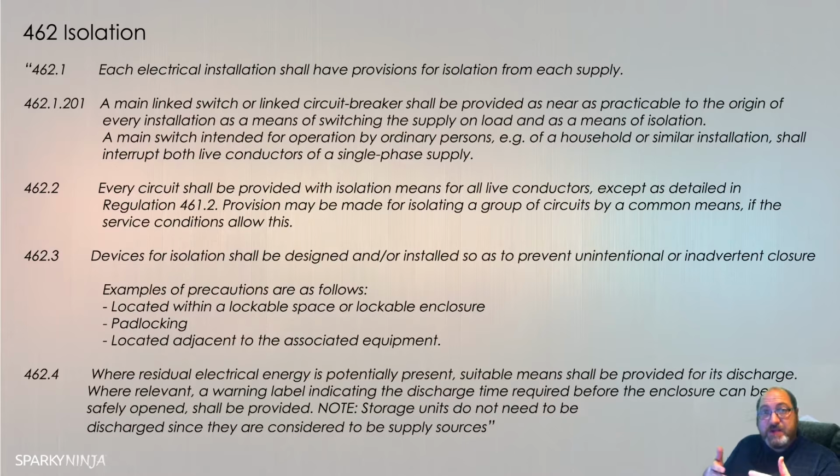The capacitor stores charge. If you work with power factor correction equipment or with any other electrical equipment that has a significant quantity of stored capacitors, maybe it's an on-site rules procedure or something that says along the lines of, at a point of isolation you must then wait 10 minutes or so to consider discharging of the residual energy. What we're not supposed to do is short it to earth, because that's obviously an unsafe working practice.